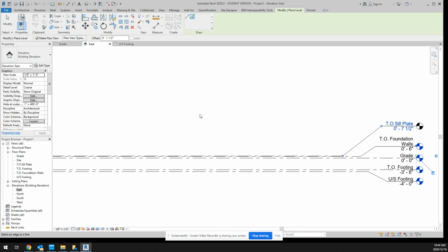So again, I don't think I specified what the floor system will be. We've talked about 2x10 construction in the lessons, which are 9.5 inches. We talked about subfloor being 5/8 thick. But what I'm going to say for this project is, if everyone just uses a 9.5 inch value for their floor joists and uses 3/4 of an inch for your subfloor, it just makes the fractional values in your work a lot easier. So if I have 9.5 and I add 3/4, I have 10.25 inches.